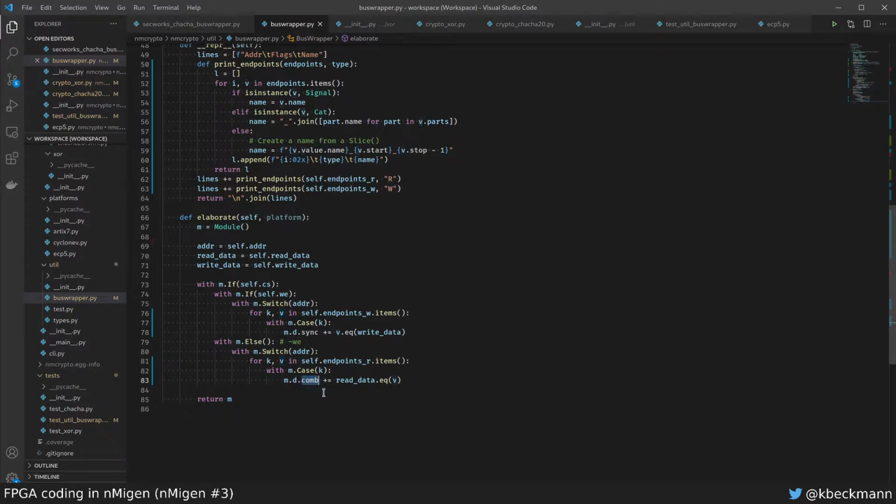If I'm using sync here, it will be delayed by 1 clock cycle, and it will use up 32 more bits as sort of an output buffer, which might be what you want, maybe not. I'm not sure.